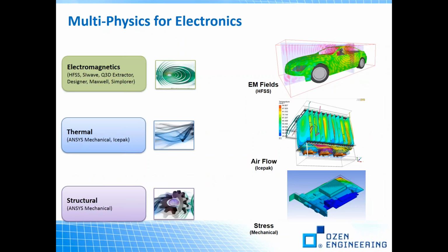One of the ANSYS capabilities is multi-physics simulation. If you are using HFSS for 3D electromagnetic modeling, HFSS is integrated in Workbench for coupling electromagnetic effects into multi-physics analysis. Basically, you can couple HFSS through Workbench to ANSYS Mechanical for thermal analysis or structural analysis. So you can do the analysis for temperature and deformation as well. This integration allows engineers easy data transfer and simulation management.